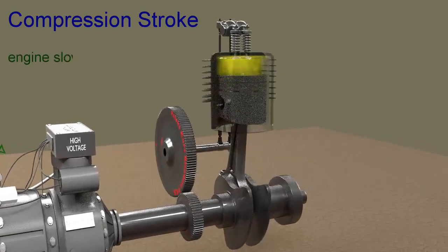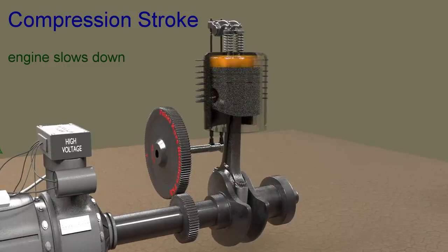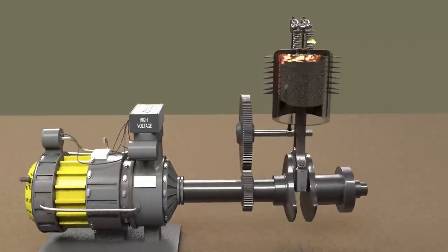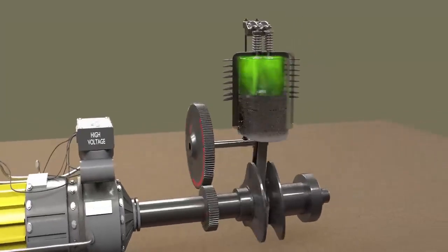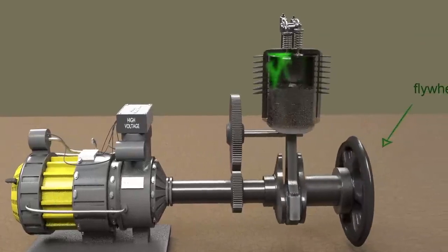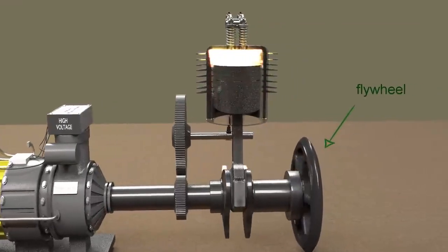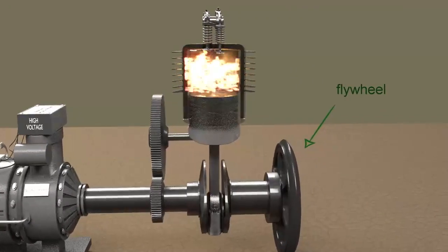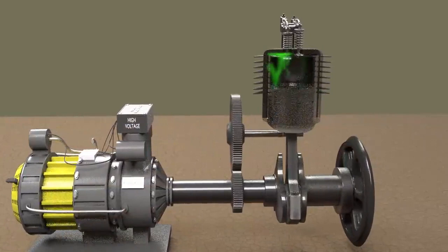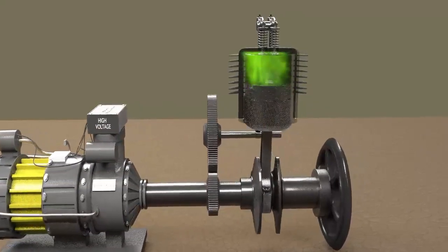This energy comes from the kinetic energy stored in moving parts attached to the engine by slowing them down, and there is fluctuation of speed. A flywheel is connected to limit this fluctuation of speed. A flywheel is a wheel with high moment of inertia, which means more energy is required to increase or decrease its rotational speed, or in other words, to accelerate or decelerate it.